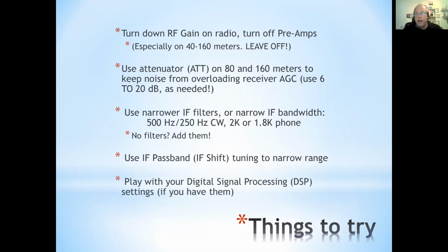And if you've got a modern SDR radio with what's called digital signal processing, DSP, for example, the FT-450 or 450D has a little contour. It's got a DSP setting. It's got all these different controls you can play with. Learn how to use them. Play with them. The manufacturers spend a lot of time and a lot of research putting these mitigation techniques into your radios. Learn how to use them.